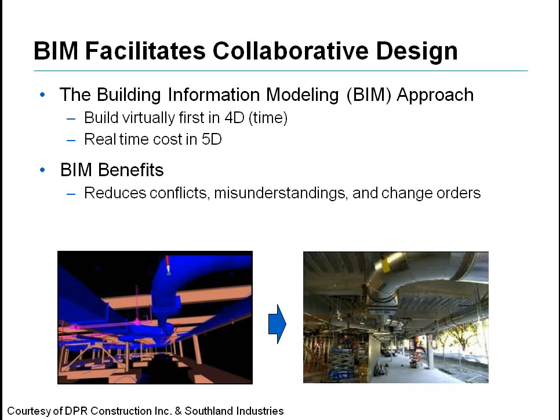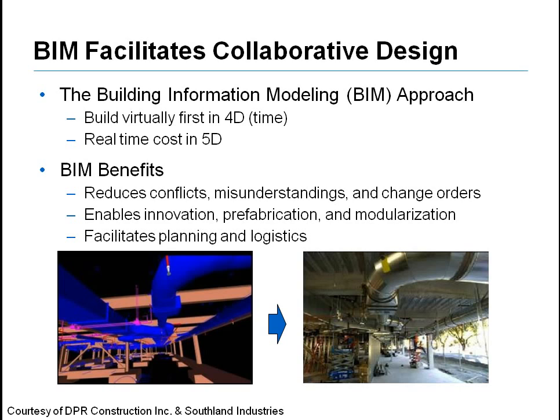A mature BIM approach includes the elements of time, cost, and parametric data for the total life cycle management of the facility. The additional benefits of BIM include designing for increased off-site fabrication, early end-user approvals, early agency reviews, better field coordination for just-in-time delivery, pre-planning for scaffolding and crane locations, and work sequencing, just to name a few.